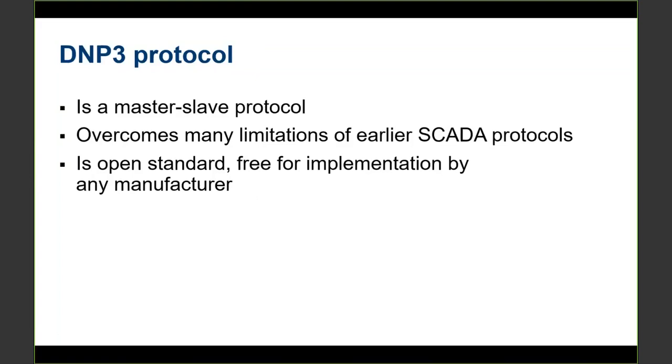So the DNP protocol, DNP3, is a protocol that defines communication between master stations and slave devices with focus on interoperability and reliability. DNP overcomes many limitations of early SCADA system protocols such as Modbus, and it is an open standard by the DNP user group, and it is free for implementation by any manufacturer. Now the DNP protocol is IEEE standard number 1815.